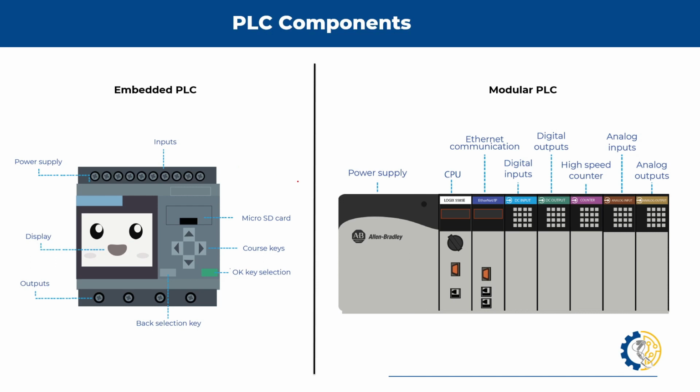The industry, obviously, and also the PLCs. In our control devices, the ones that we are going to control, the signal that we assign to this device is going to be 24 volts DC. Now, what would happen if we change it to AC? We could do that, but every PLC is different. We need to analyze its characteristics. And we also need to analyze what voltage is needed to be fed. Be very careful with this. We need to learn and know how to identify the voltage and the range.